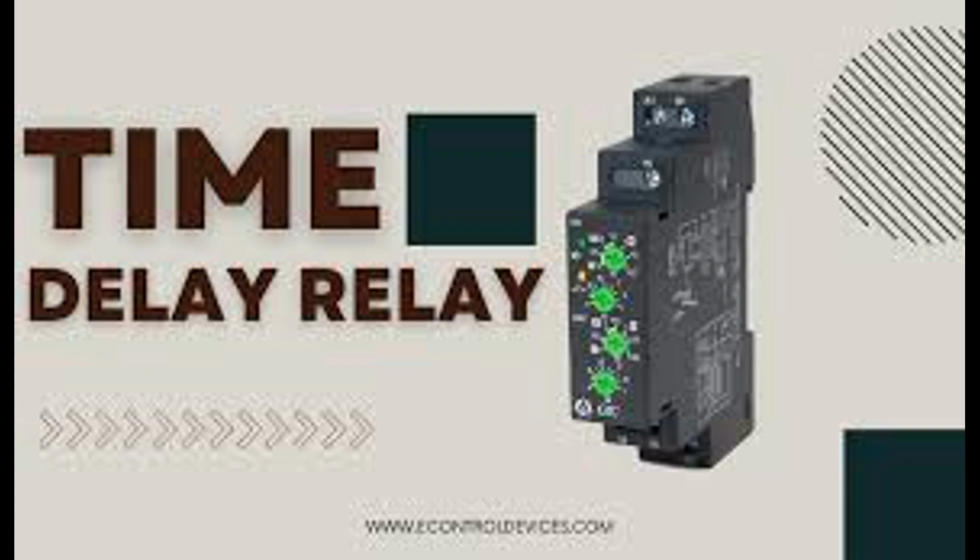Thermal protection. Thermal protection mechanisms monitor the temperature of the relay and disconnect the circuit if the temperature exceeds a safe threshold, preventing overheating and thermal damage. Thermal protection may involve temperature sensors, bimetallic strips, or thermal shutdown circuits that interrupt the power supply to the relay until it cools down to a safe operating temperature.